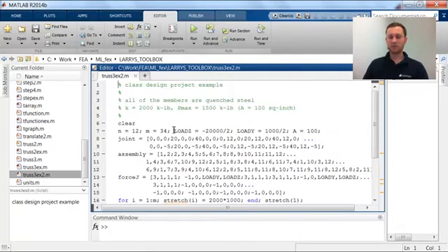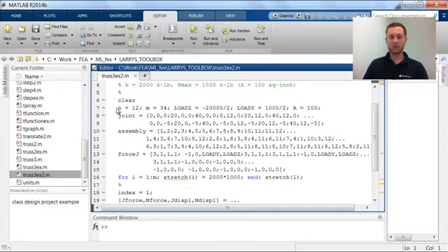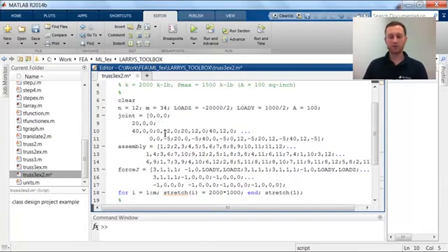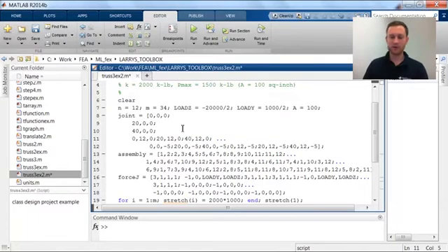So what we see here, it's an example. We talk about an example with 12 nodes and 34 truss elements. Larry already introduced some loads. And what we see here, he calls the vector joints. It's nothing but a 12 by 3 vector giving the node coordinates. So I don't want to put it all down, but first node is at position x0, y0, z0, and then going down 12 nodes. The assembly is exactly what I've introduced to you as connection or as an ID matrix.